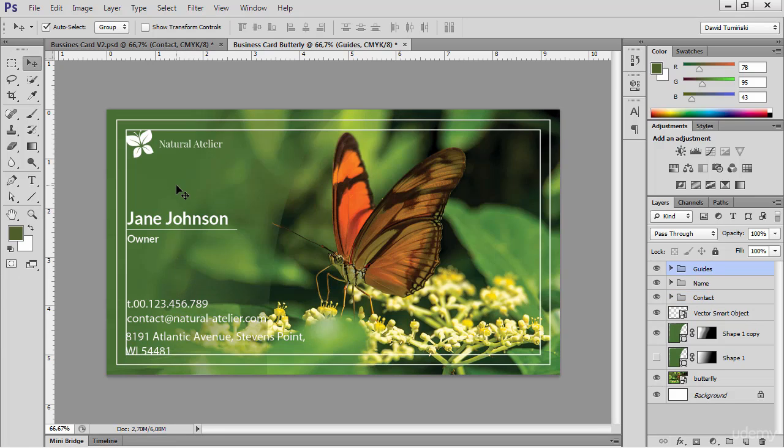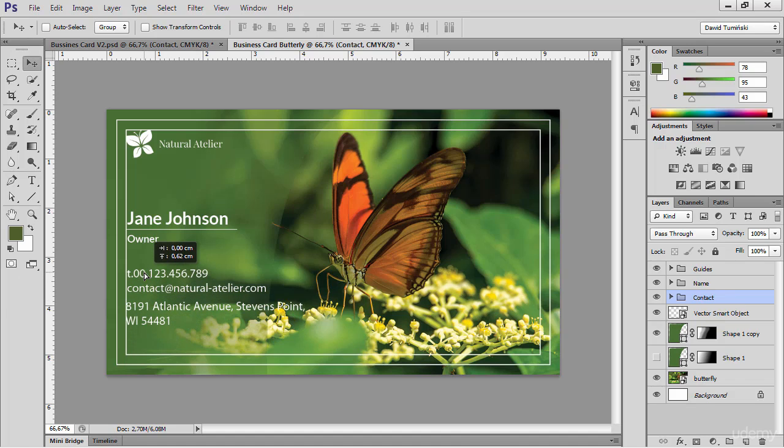If you see something like that happen to you inside Photoshop, like it's happening right now, that's most probably because you have this auto select option turned on. It tends to be useful when you have a lot of different elements created on your canvas, but this time it's not helping at all. So I'm going to deselect it, make sure that I'm on the proper layer, and move this a bit up to somewhere here. And my name, I think I'm going to leave it like that.